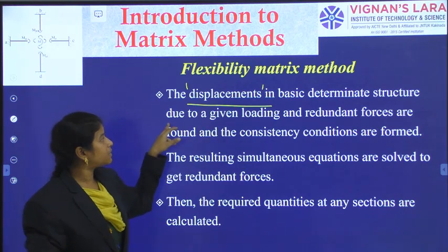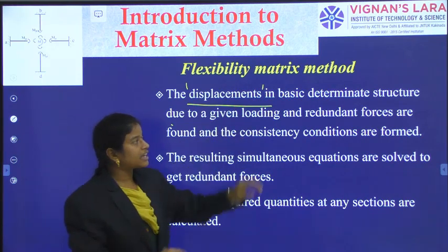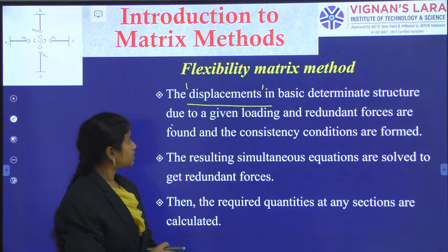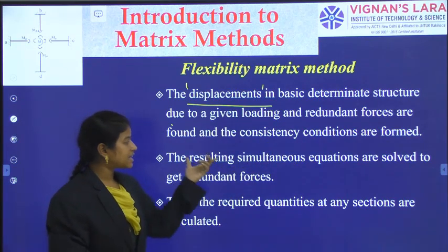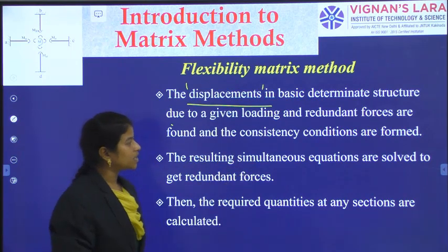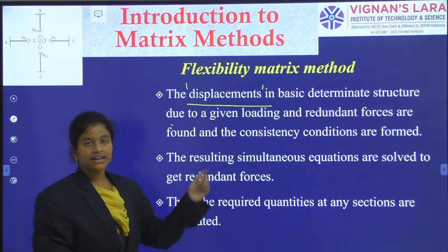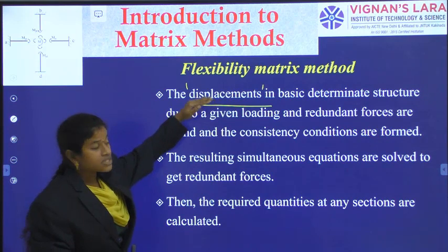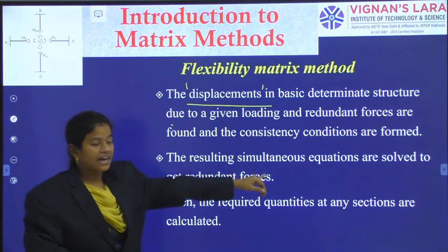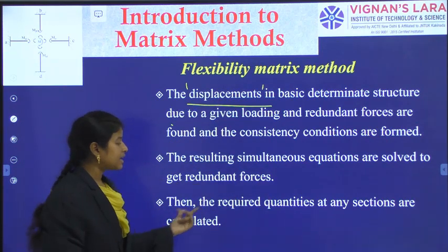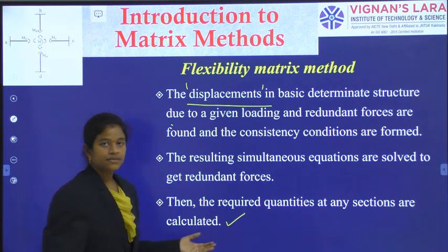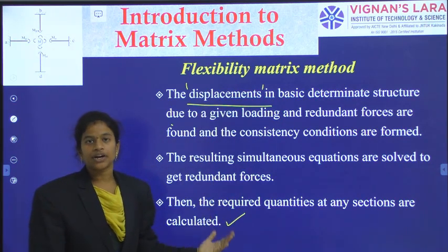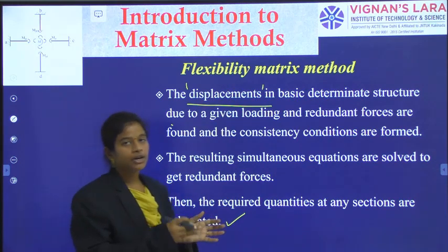The resulting simultaneous equations are solved to get the redundant forces. Using the concept of displacements, I am analyzing the redundant forces. Then the required quantities at any section can be calculated. So step by step we are making the indeterminate structure a determinate one.